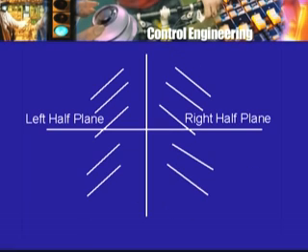And so the conclusion that we can draw is that on the pole-zero diagram, look at the poles of the system. If the poles of the system are all strictly in the left half plane, then no need to worry about this part of the response. Things are all okay. But if the poles lie on the imaginary axis, including the origin, or lie in the right half plane, then that is cause for worry. The system requires to be changed or some modification requires to be introduced, maybe some parameter needs to be changed or some feedback element is to be introduced or changed, and so on.